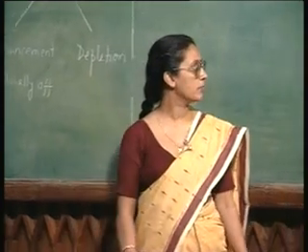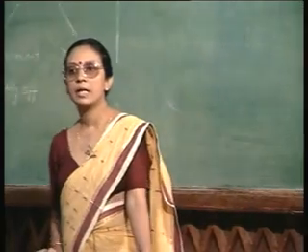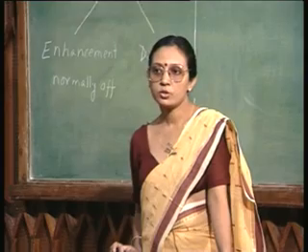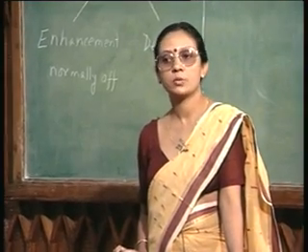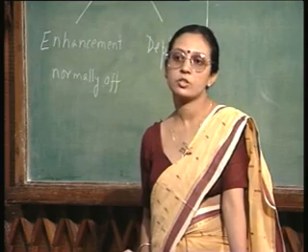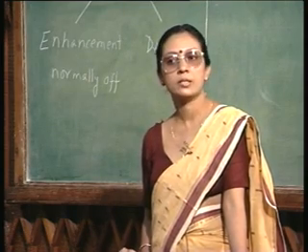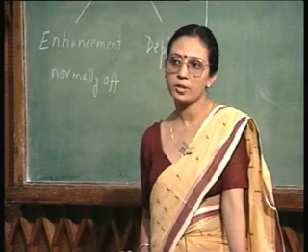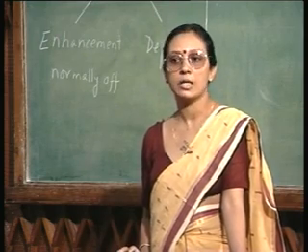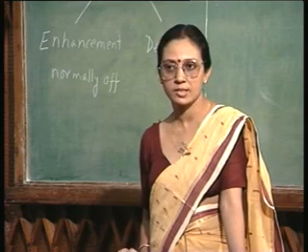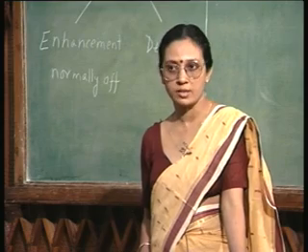Threshold tailoring implantation is done only in the channel region in order to realize a particular threshold voltage. We will discuss more about the threshold tailoring implant when we discuss ion implantation technology. For the time being, the only point I want to stress is that ion implantation has become a very useful processing step in MOSFET technology.